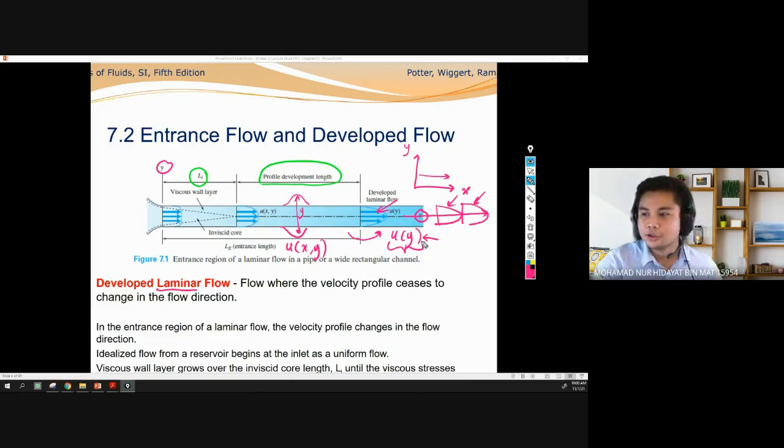Okay. So basically, this is about the internal flow. It is very easy, right? Remember that once you open up your pipe, try to imagine, along the pipe, there are full of zombie with social distance of 1 meter. And then the pipe starts to flow until at certain extent, the flow becomes the entrance length. From here to here becomes the entrance length. After passing through the entrance length, it becomes developed flow. It becomes matured flow. The flow can walk, can run, can stand.